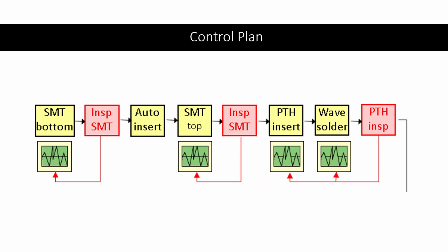The control plan defines all the controls, visual, test, etc., installed along the value stream in order to catch the defects as soon as they are produced, in order to correct them, and give immediate feedback to the step producing them. These controls have a cost, both in terms of manpower and flow drop, so they should be minimized and installed just where and when they are required. As the process is improved, by solving the root cause of the defects, controls can be removed or installed somewhere else. The control plan is, therefore, a living document.